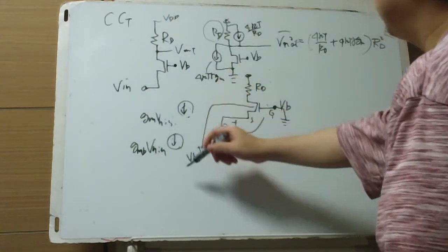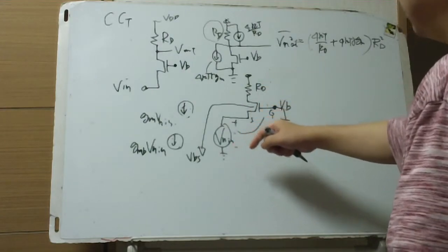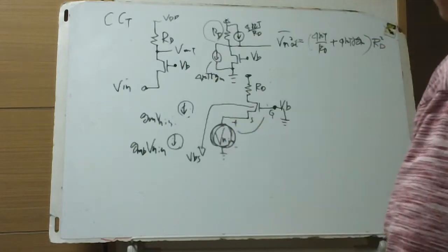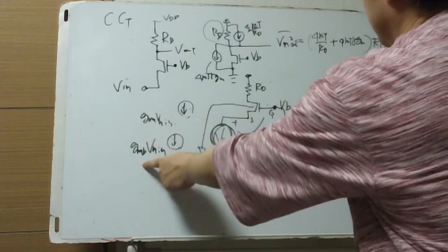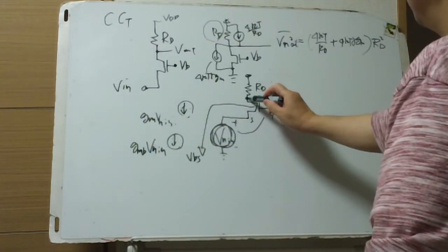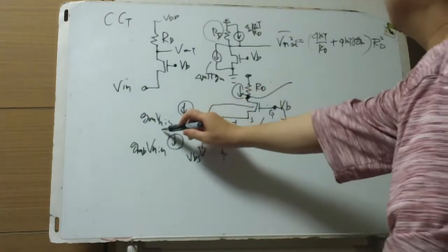So in the same direction as the back bias effect and channel effect, noise is transferred with transconductance gm and gmb, so there appears a current noise of this sum.